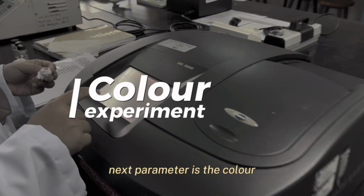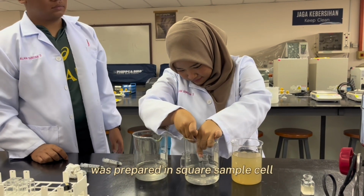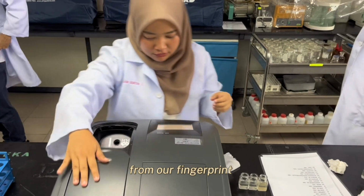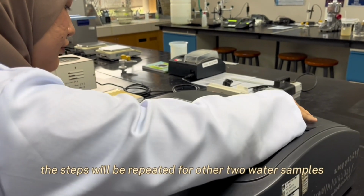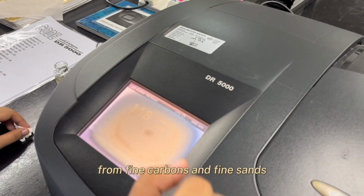Next parameter is the color. 10 ml of raw water sample was prepared in a square sample cell. The cell will be wiped with tissue to prevent errors from our fingerprint. Code color 125 was selected in the spectrophotometer to obtain the color value in PtCo. The steps will be repeated for the other 2 water samples from fine carbons and fine sands.